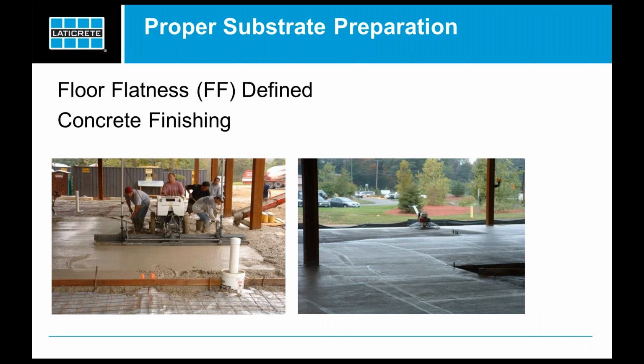We obviously start with a good substrate. We want to make sure that it's solid. We're going to talk about concrete first. And we really want to make sure that we have a nice, smooth, flat surface, because as you saw, those panels are larger and larger. And as they continue to get larger, your concrete has to be even flatter and even more in tolerance in order to accept these types of finishes.